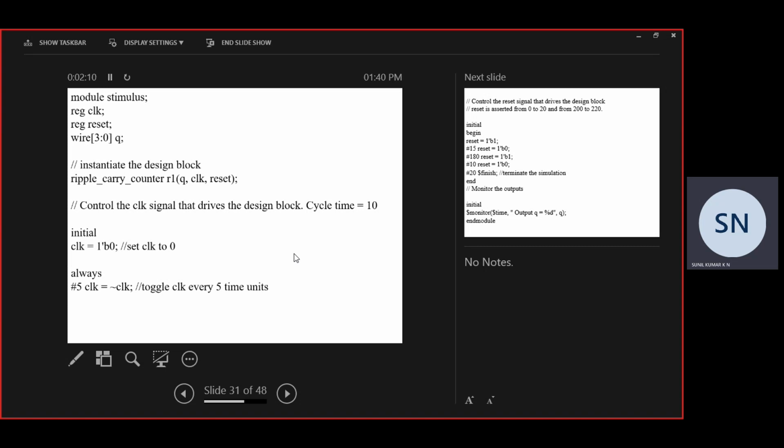It is dependent upon clock, which is one of the input signals. Always you should write clock is equal to 1'b0, clock is equal to 1'b1 whenever you want to write in the stimulus program. That will be very big and time consuming, and it will not be a good thing to write in the program. So defining the variable, what I am going to do is, the clock signal will be defined as a program. That means we are generating a clock.